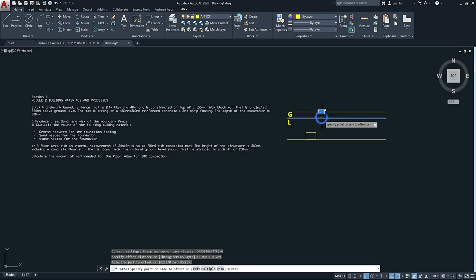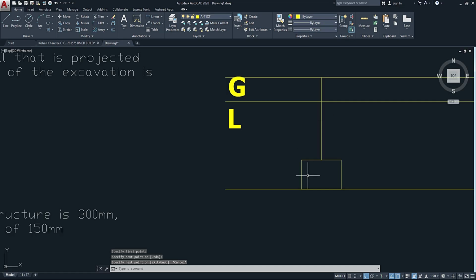So we know that the block wall, the chain link fence, starts above here. And we also know that the concrete block wall goes all the way up to this level here. I've just drawn a line in the exact middle or center of my pad footing, and I'm going to offset again, 0.075. Now we're there. So one on that side and one on the other side, and that there is our block wall. We'll keep this middle line here that will represent our steel in the middle, and we'll continue from there.